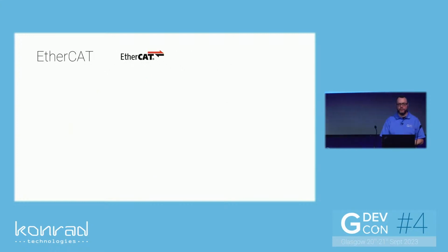It's a new kid on the block, developed originally by Beckhoff. Now, again, that's been moved off to an independent organization, the ETG, around 2003, it says here. Again, it's based on Ethernet networks. It's very simple to implement. It also has automated network device identification. In my opinion, it is the better of the three, and I think it'll actually overtake the first two. So if I was to pick one, it would probably be EtherCAT anyway.